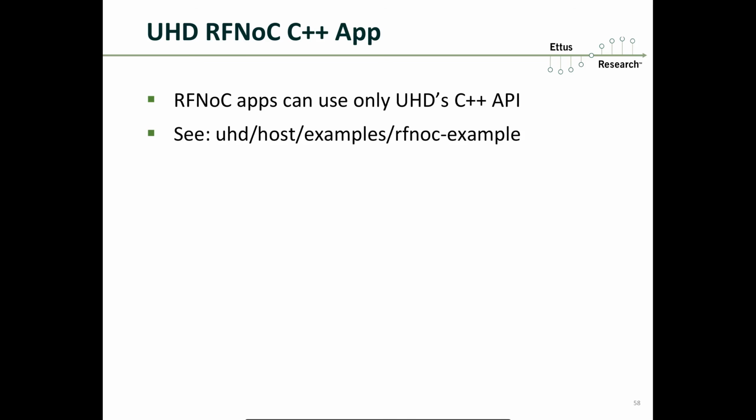Now, of course, if you're using rfnoc-modtool, you do need GNU Radio because that's what's going to be used to set up that out-of-tree directory structure, and that relies on gr-ettus, which of course relies on GNU Radio being installed. But in this case, we have you covered when it comes to having an example design already existing, so you don't have to worry about having or using rfnoc-modtool and having GNU Radio installed.